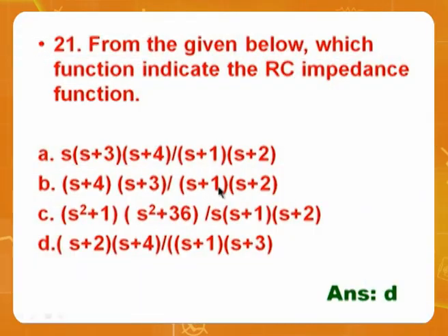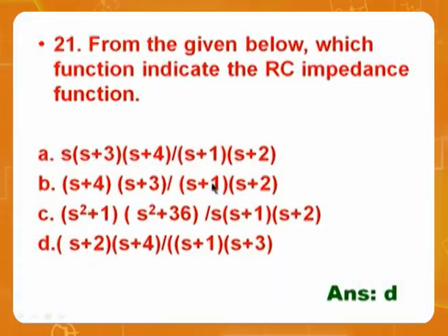And if a system is unstable, such systems we never synthesize. We need to synthesize or design a circuit which is unconditionally stable. Therefore, I already told you, you should not have poles consecutive. Indirectly, I told you, poles and zeros must be alternating. So what is happening is side by side, consecutive is there. That's why B is wrong. Otherwise, B is also correct.